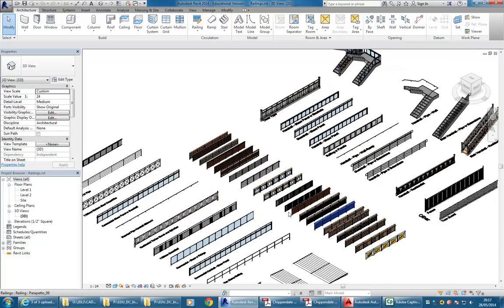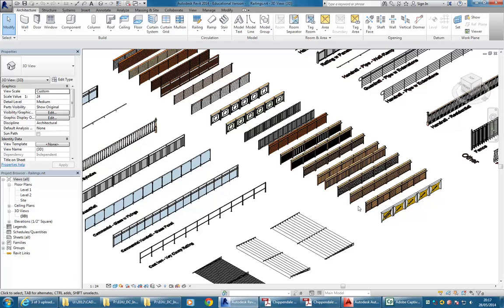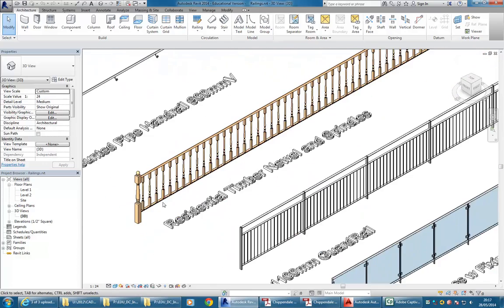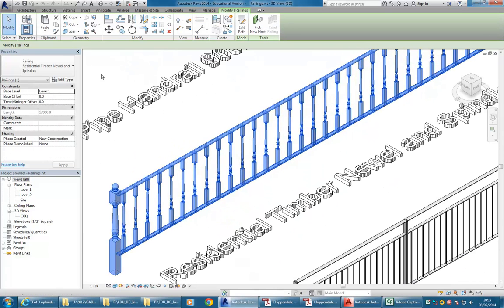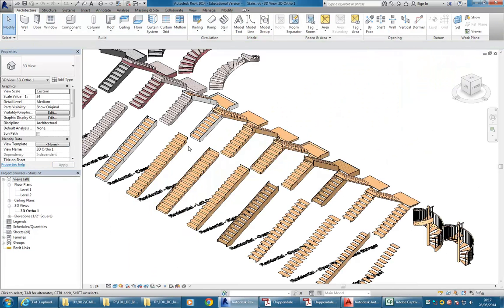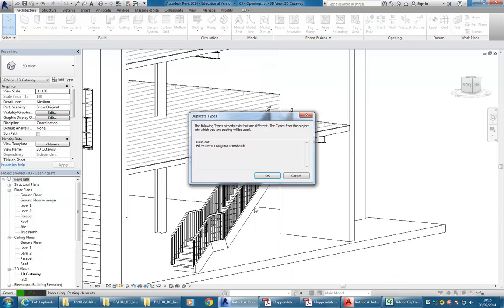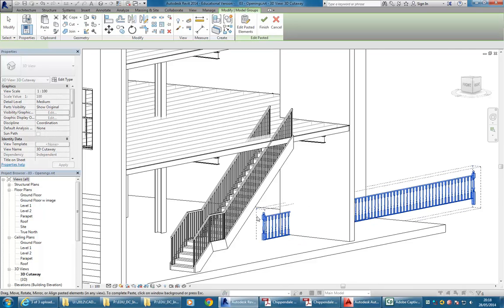Okay, so all you need here is a timber balustrade that looks old-fashioned, essentially. It wouldn't really matter which, but this one here is close enough. So I'll just choose it, and to get into my project file, Control-C, or copy to clipboard, Control-Tab, back into your project, Control-V to place, and then delete.